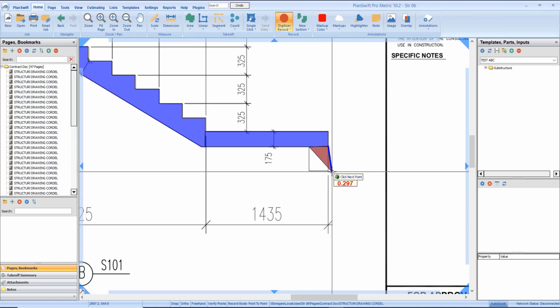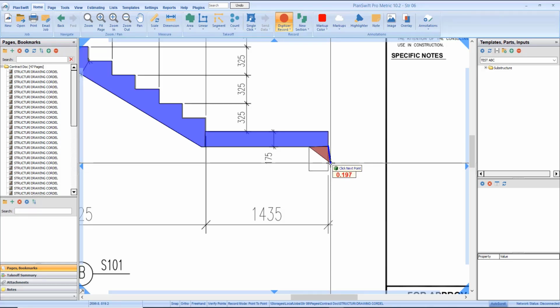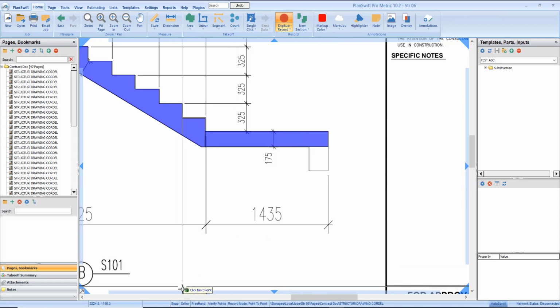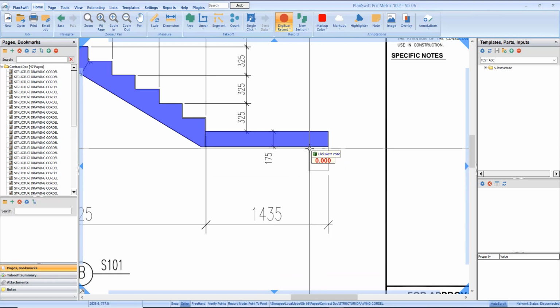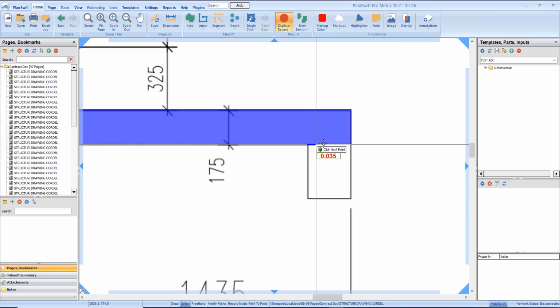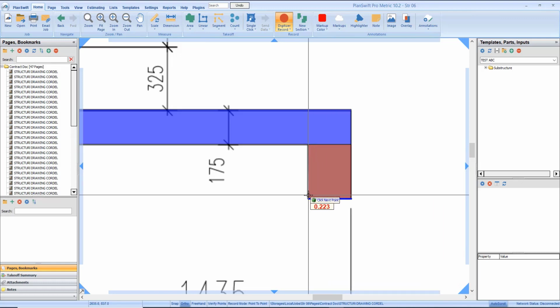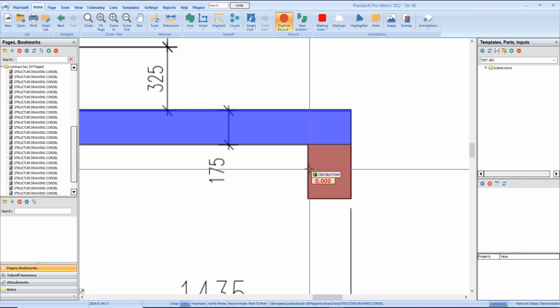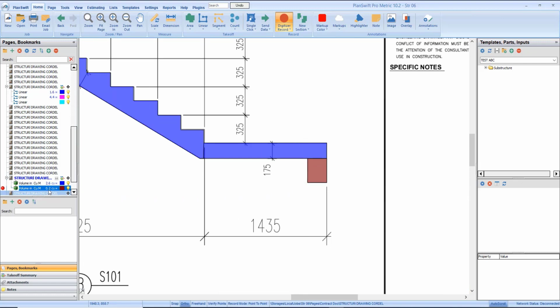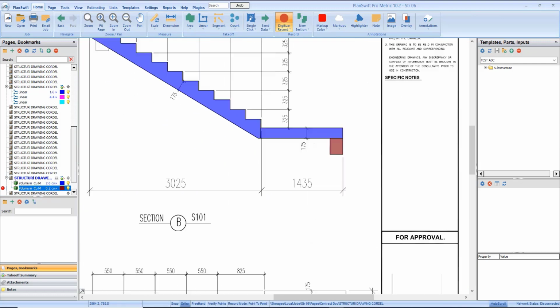You can see that my line is going in a zigzag motion. So what I have to do, you remember what I did initially, I turned off my auto. So click my backspace twice and turn on this very auto, and once I turn it on, my edges are able to snap correctly to each and every one of these ends. All right, so with that it is 0.2 cubic meter.